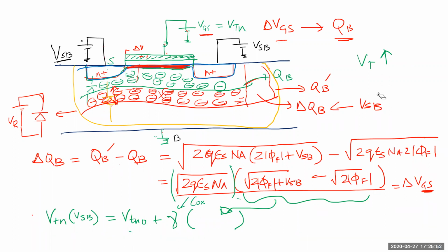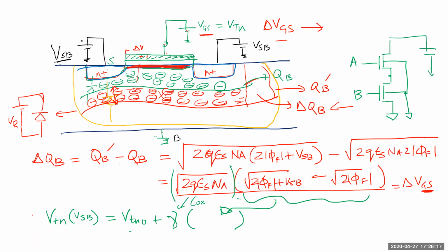All of you are a little bit familiar with gates now. So in your NAND gate, you have two NMOSes, right? This is connected to some A input, this is connected to some B input. So this bulk is usually connected to ground. So is this bulk, right? So typically, let's say this is conducting some current, discharging this gap.